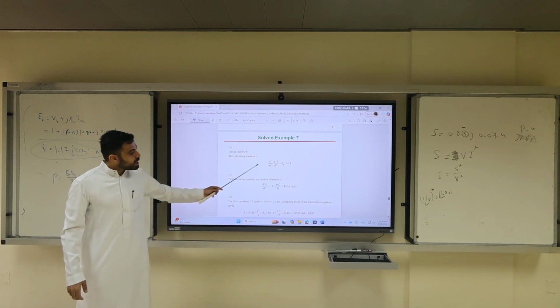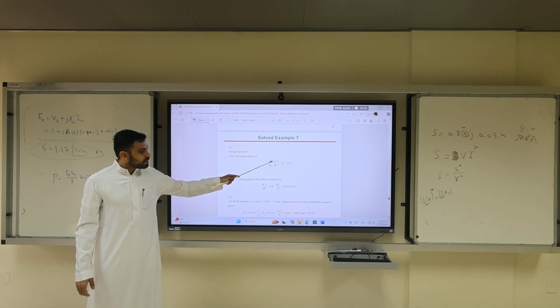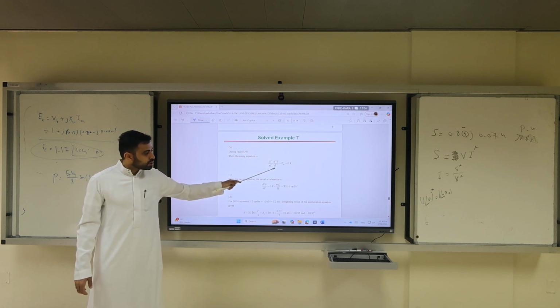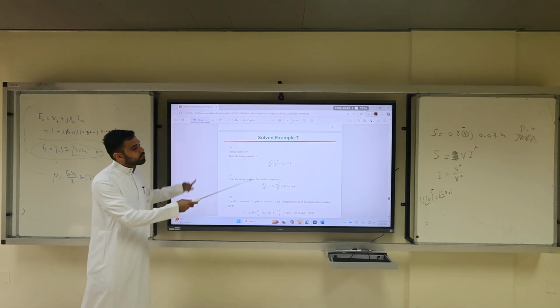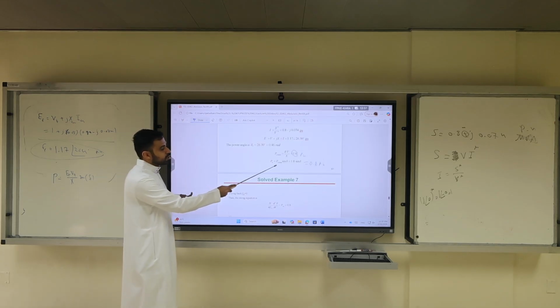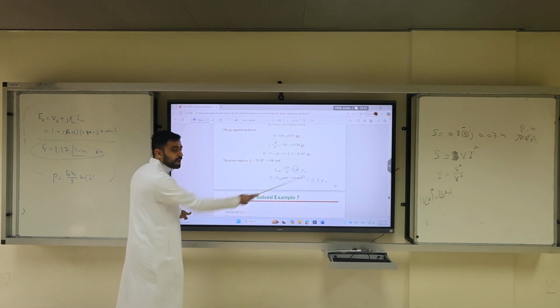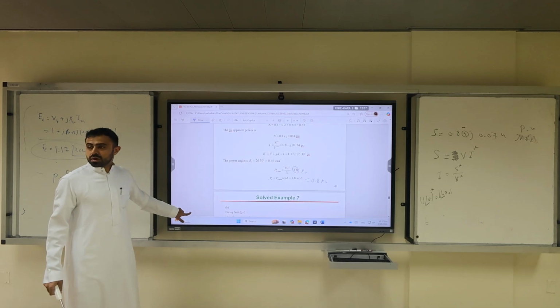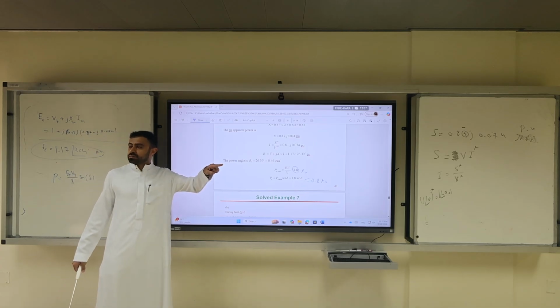So the swing equation becomes H over pi F0, which is 60 Hertz, times this acceleration equal to mechanical power. What is the mechanical power we calculated before at part A, not maximum, at this angle? 0.8. So at equilibrium it will be 0.8 minus 0.8.